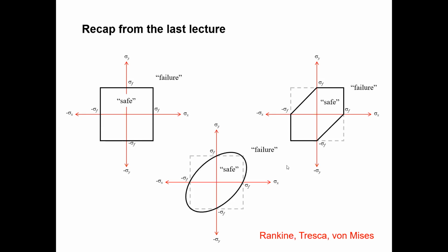Those theories we can use, but when you use one particular model, you should know what the material is, because the first one you can't use for ductile material, but the last one you can use for ductile material. Tresca theory, that means the third method, you can use for both materials. That's very suitable if your material is unknown, you can use Tresca theory to find out the failure. So you can find out, when a particular stress system is applied on the element, is it safe or failure using this boundary line?